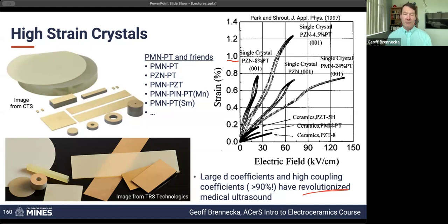So obviously it's still a ceramic. It's still relatively stiff compared to polymers. But for a ceramic, this is really squishy. The elastic modulus is quite low, and that's how you're able to get so much strain. That also relates to the very high permittivity, because that low modulus means you apply a field and you can get those bonds to stretch a lot. So you've got soft bonds that you can pull apart with that electric field.